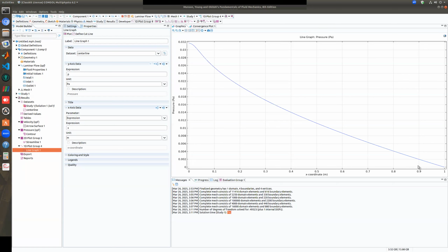And then I can check whether that dpdx and the other variables that I entered, like viscosity, density, average speed, and all those things, match with the analytical solution, with the theory or not. And most probably they do match, right? So I can just plot also U here. I will change this pressure to U. So I will plot the x velocity component on the same streamline.